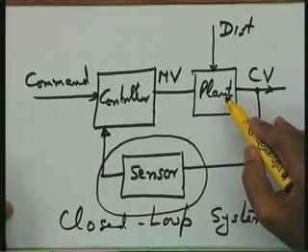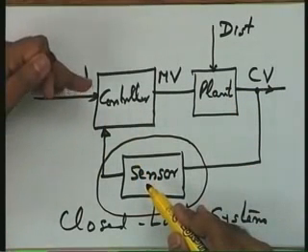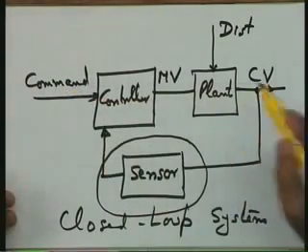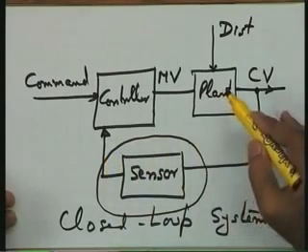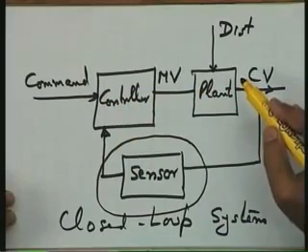So, the plant and the controller, in addition to getting the useful signal about the command signal and the controlled variable, get this noise signal, which is a high frequency signal, and the plant will react to that signal as well, and your control may not be effective. This particular problem was not there in the open loop structure. However, a suitable noise filter can be installed in the loop, so that this particular problem of noise can be taken care of. Okay? Now, once we say that the noise problem is taken care of, then let us see what is the requirement on the controller.